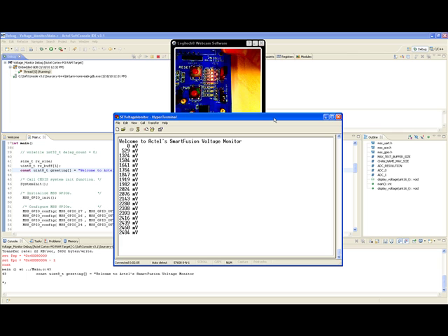Rotate the potentiometer clockwise again to reduce the voltage, and notice that the LEDs switch off, coinciding with the threshold flag voltages set in the SmartFusion ACE configurator, and the actual voltage is displayed on the HyperTerminal.